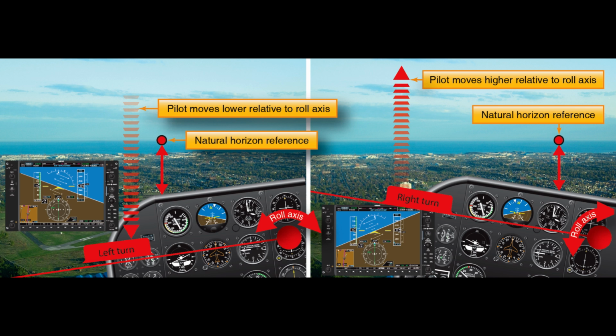2. Best rate of climb, VY, produces the most altitude gained over a given amount of time. This airspeed is typically used when initially departing a runway without obstructions until it is safe to transition to a normal or cruise climb configuration.